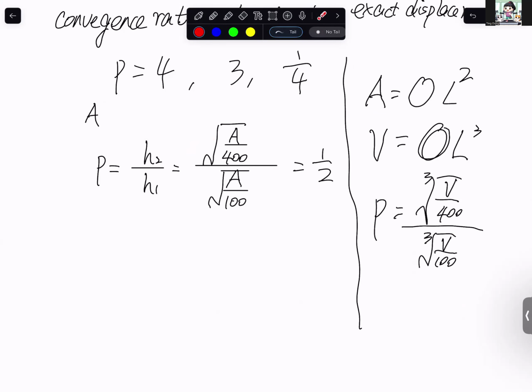What if they're differently shaped? A combination of square element and triangle element, we normally don't do that. In real life, as an engineer, we decide what element type we want to use to be most efficient and most appropriate for our application. We normally use one type of element to model the whole problem.